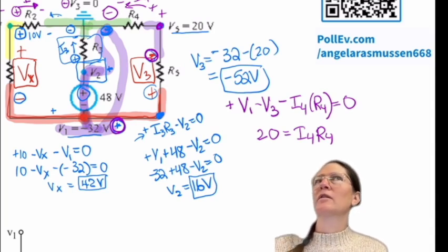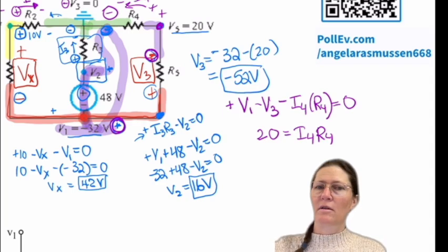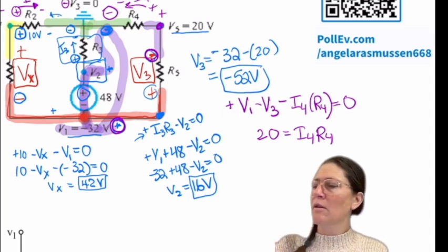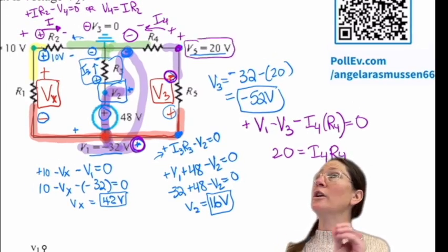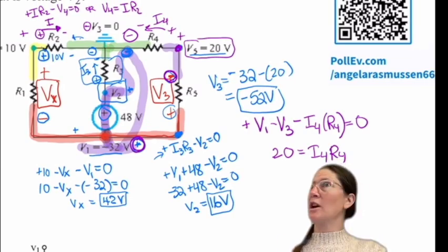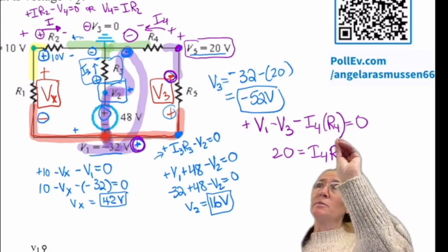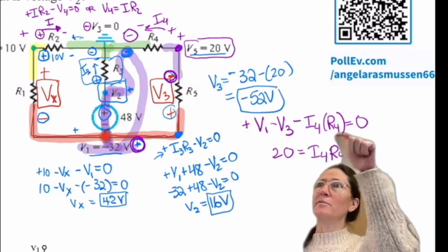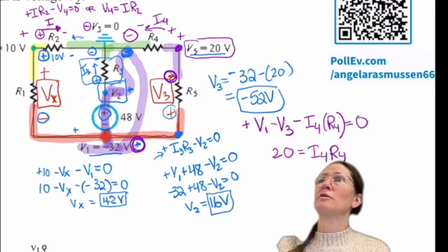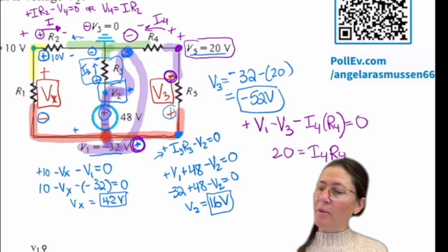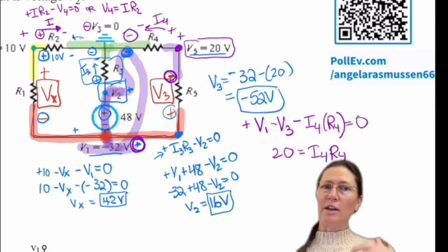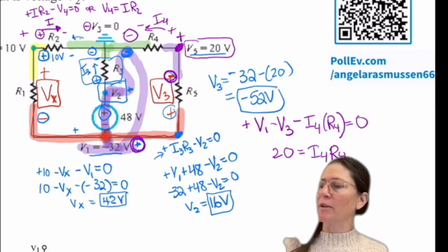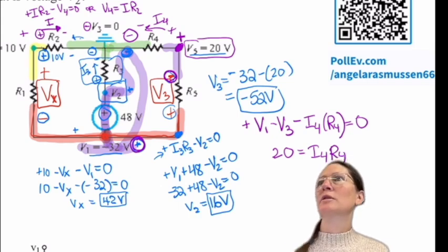Yes. How did you figure out the charge, the plus or negative, of the node at the top and the node at the bottom? So V5, anywhere in a circuit that you just have a dot, that's always going to be positive. It's always implied to be positive from that location in comparison to ground. So the plus there next to the V1 is because that's a node, and then to ground. And then also at V5, that's a plus because it's the node to ground. So that's always a plus at that location.